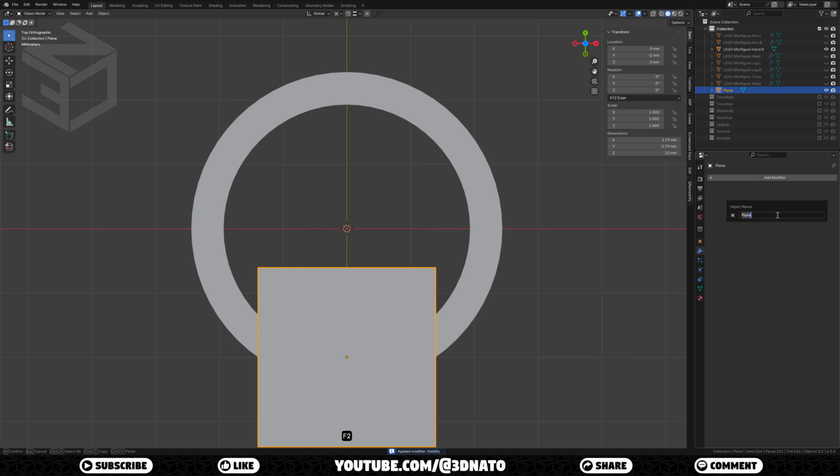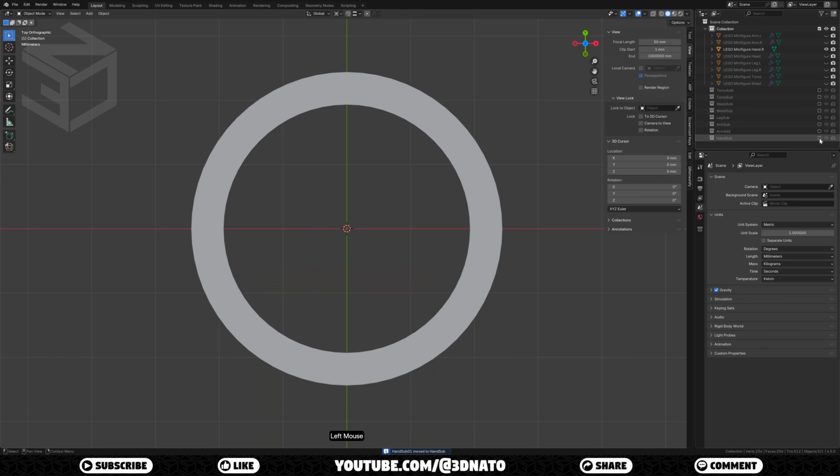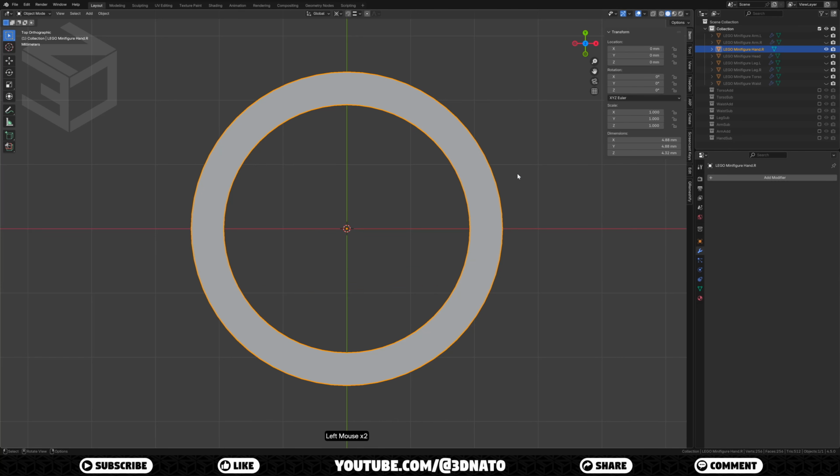Now press F2 to rename and rename it handsub01. With the mesh selected, press M to move to Collection, click New Collection and rename it handsub. Now uncheck it to exclude it from View Layer. Select the hand, go to Modifiers, add Modifier, Generate and add a Boolean modifier.